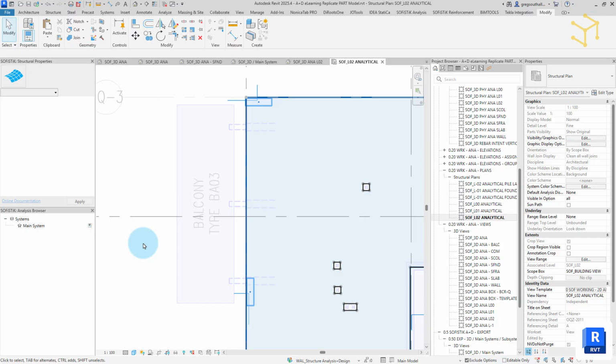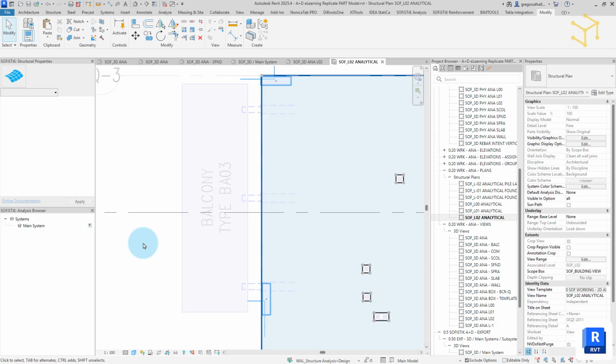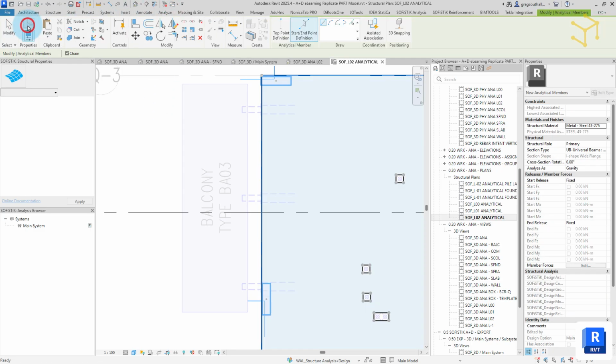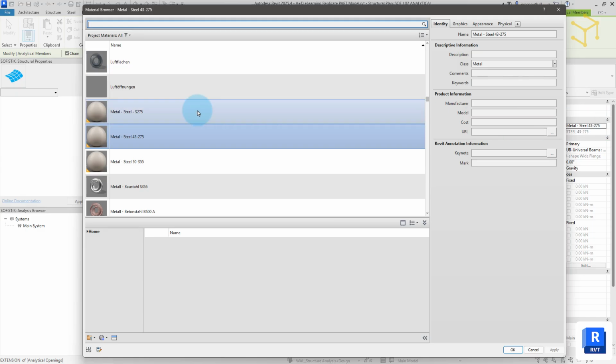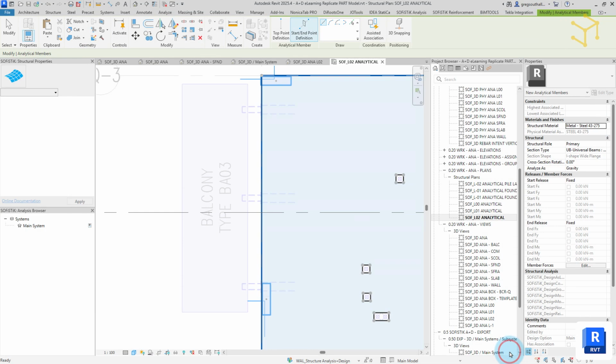We'll model a single support point representing this system, and in step 5, when we apply the loading to the model, we'll add loads to this single support before we then duplicate or generate a group for the purpose of further duplication. Here we select a suitable representative support member, and place whilst in a 2D structural plan view. We then apply the short form name to the SOFiSTiK filtering ID and assign the member grouping.